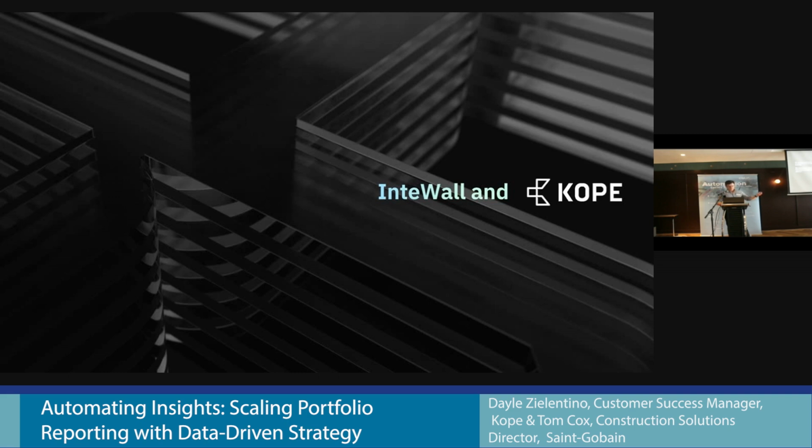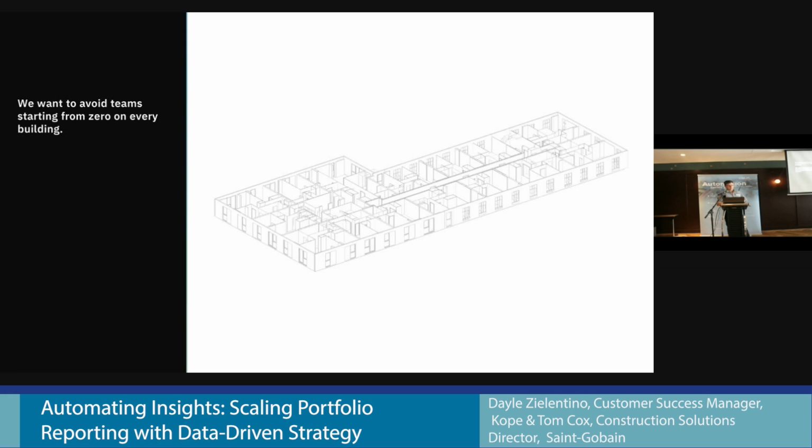What we do is we take that model, we apply those panels, so we apply Interval to that building rapidly, and we can immediately see where we have concerns. So actually your floor to ceiling heights here are larger than what the panel system can actually support out of the gate, and they have to be a bespoke solution. Actually, you've got a congested corner around the core. You've got 3-4 corners coming together in close proximity. Actually, the panels can't be installed in that way, so you're going to have to go with the traditional frame in that area, but the rest of your building is optimized for that.